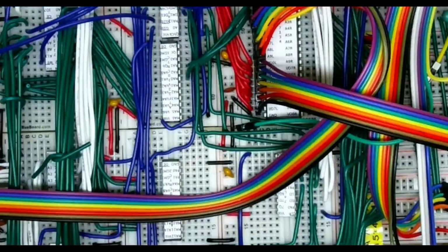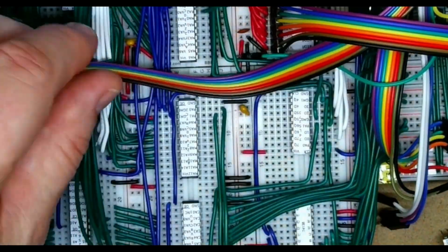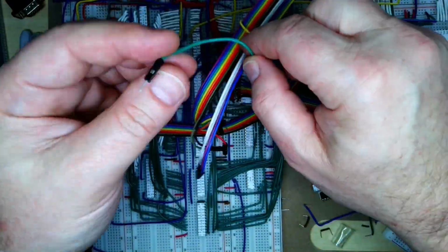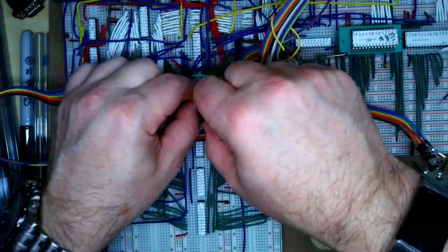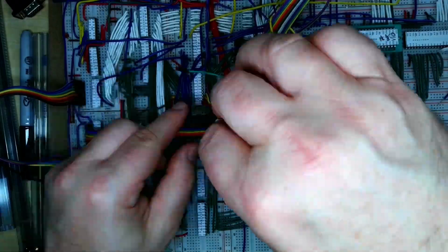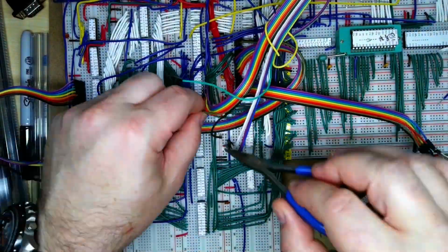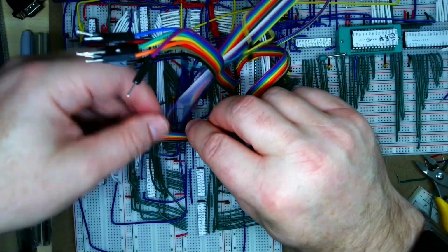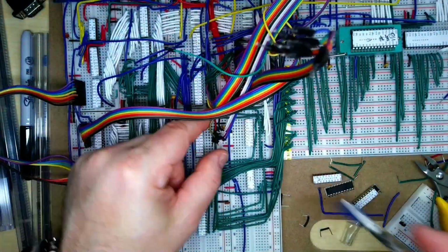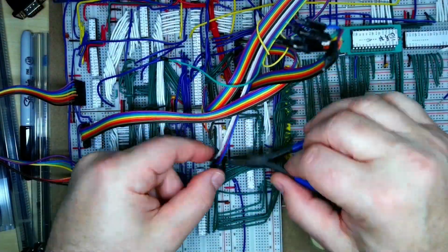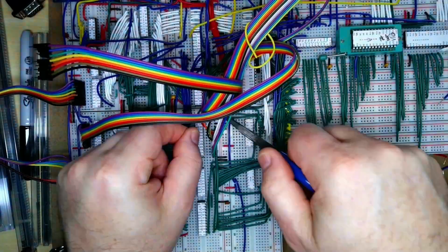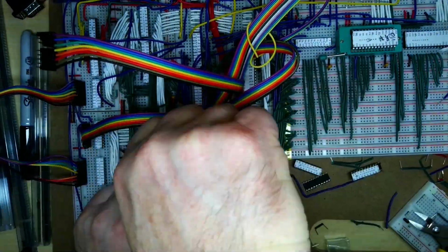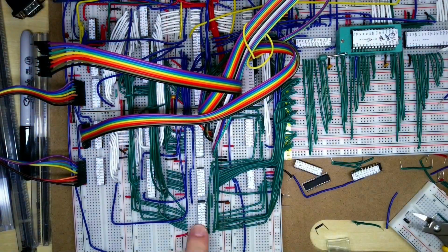So now we're going to be wiring in the various CRTC memory address lines, so we just need to sort out those. So this is the memory address 0 all the way up to, I think, memory address 12 we're using here. It's just wiring those into the input side of all the multiplexers, making sure we get those right. Okay, then there's a few extra lines there. We're actually hooking up the 3 address lines. So that's all the PLD changes done.